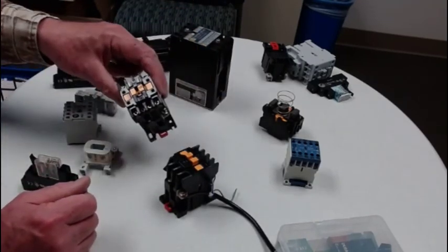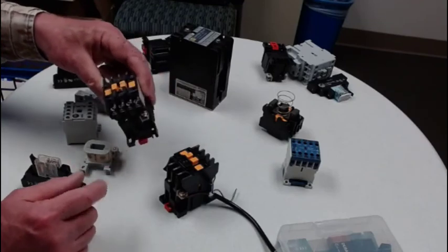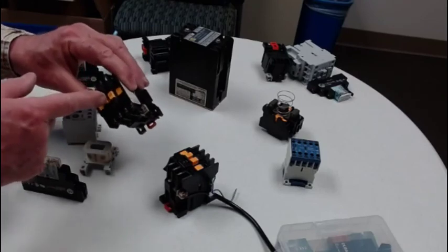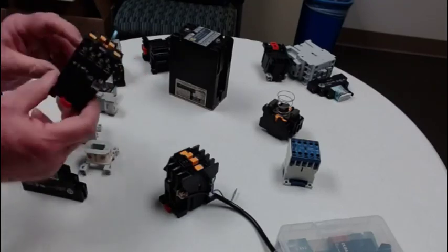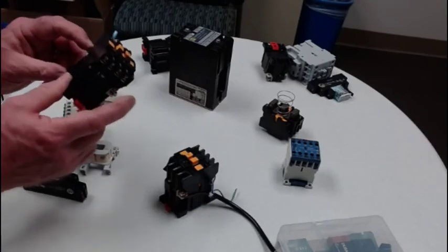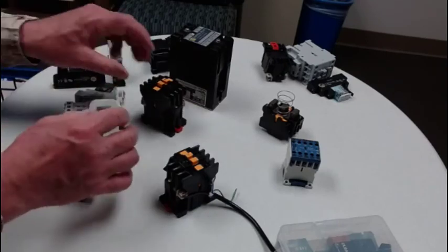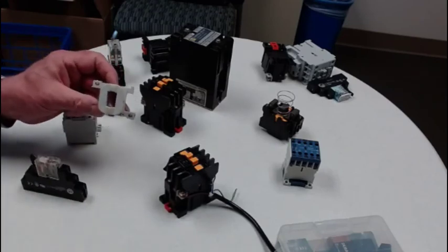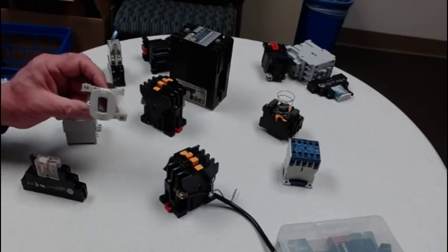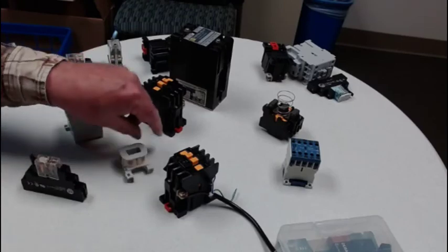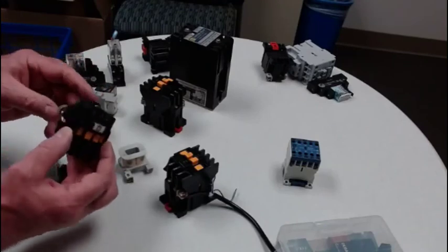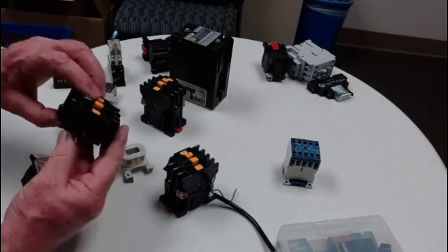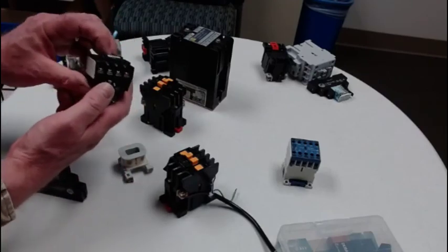This is a little bit smaller IEC version of that relay, and these have contacts in here that open and close when you energize the coil, and the coil is between these two from here to here, and this would be the coil taken out and looked at. It looks like an O, and that's what we're going to talk about, an O for the symbol for a coil. And this would be the top part, or the spring part, that would push the contacts up, and then when energized they would go down, and they would be in this down position.